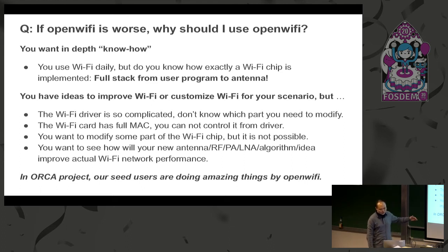So with this design, you have the full open stack, from the user program in Linux to the antenna. In the FPGA, there is also logic to control the front end and antenna, such as antenna selection, TX gain, RX AGC. Everything works just like those modules in a commercial chip.